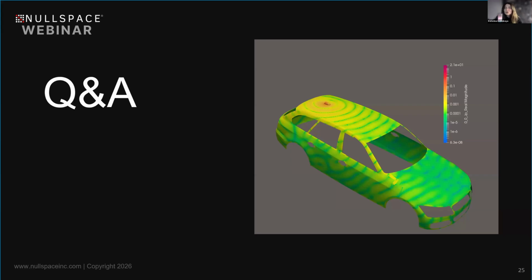It's very important not to short the antenna, to avoid a short circuit where the antenna is actually connected to the car. As Henrik explained before, you need some kind of capacitive connection there, not a galvanic metal connection, right?